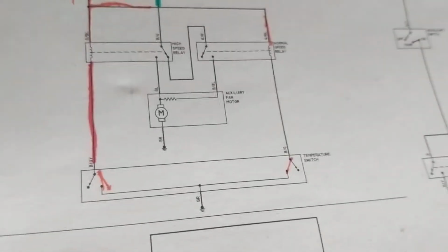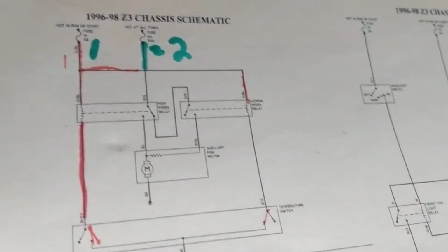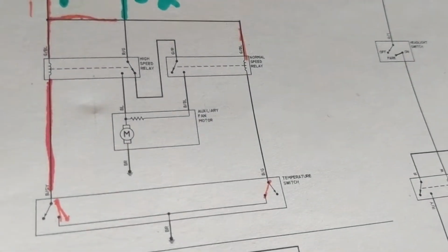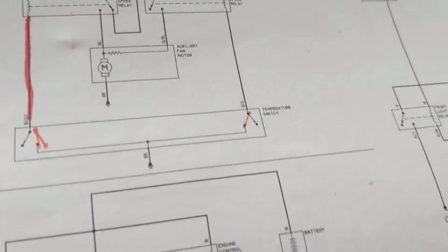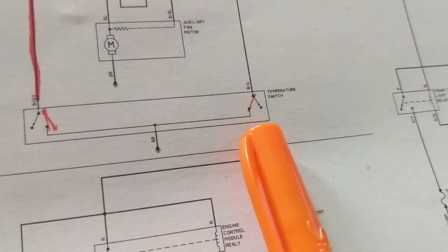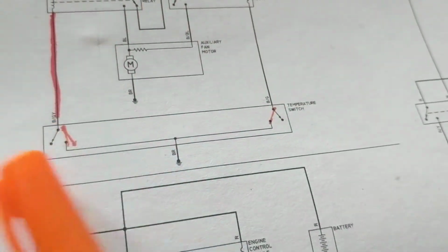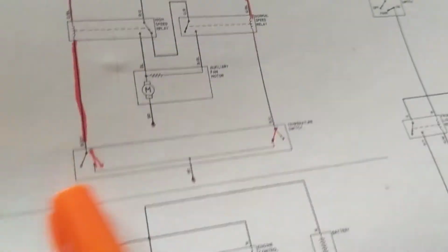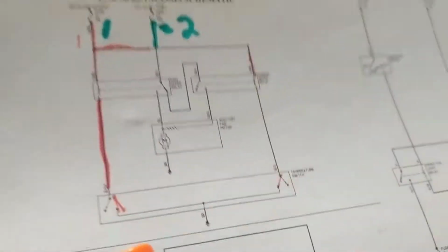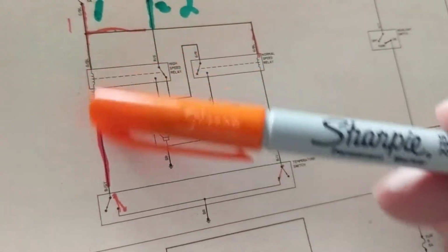Again, we're looking for how to analyze an automotive circuit. If you look at it, it's almost the same circuit as the one before. Before, if you remember, I told you a temperature switch. What's in it? Switches. Where do the switches go to ground? Why do I need that? To activate the coil. The other side of the relay has to go to a ground.